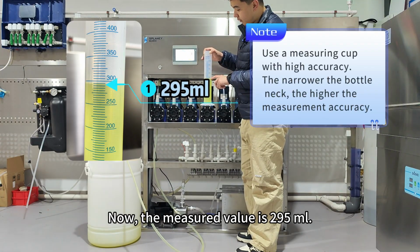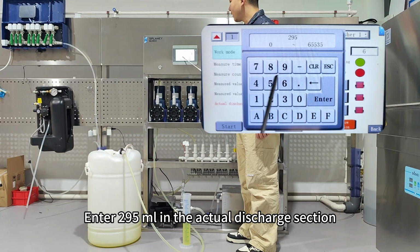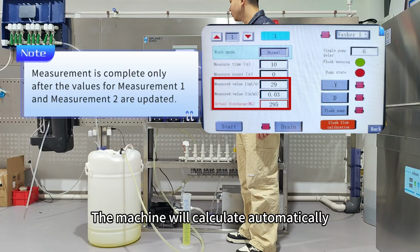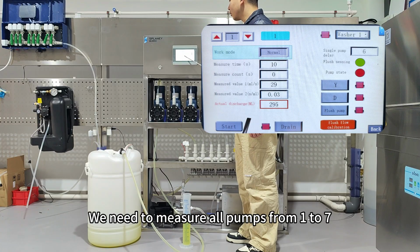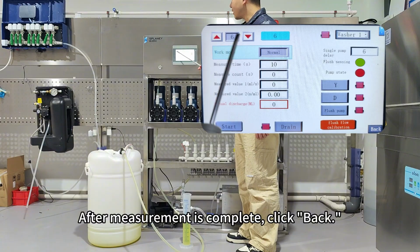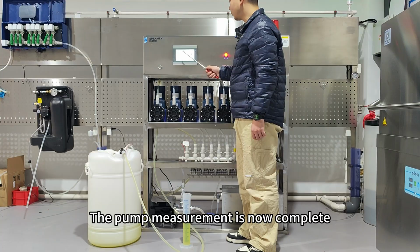Now, the measured value is 295 milliliters. Enter 295 milliliters in the actual discharge section. The machine will automatically calculate the flow rate of the pump per second and how many seconds it takes to dispense 1 milliliter. We need to measure all pumps from 1 to 7. After measurement is complete, click Back. The pump measurement is now complete.